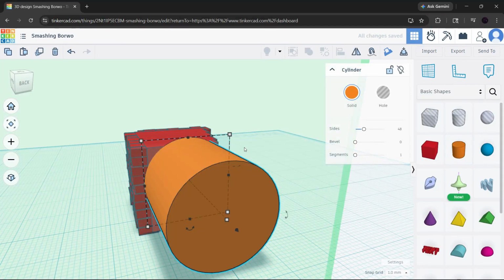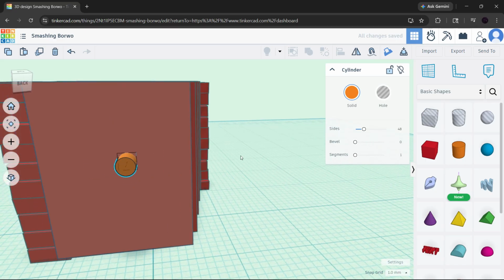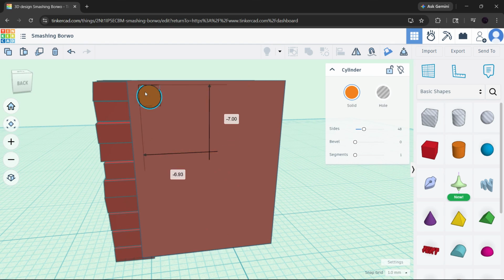If the texture looks too shallow, you can go back and adjust the hole depth. If it looks too strong, make the hole smaller or reduce the overlap. A helpful tip is to zoom in while you work so you can place everything accurately. Another good tip is to duplicate carefully, because consistent spacing makes the texture look much more professional. If the pattern needs to cover a larger area, build one section first and then copy that section across the model.